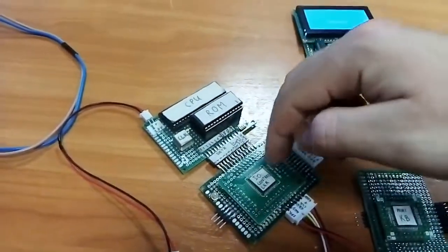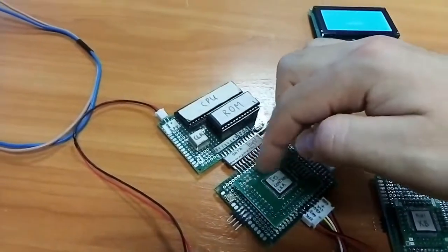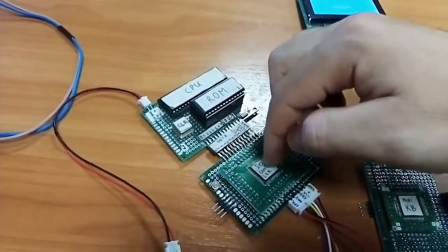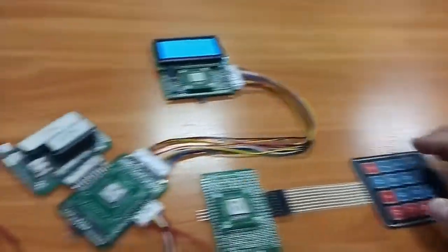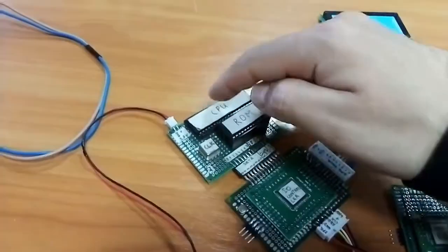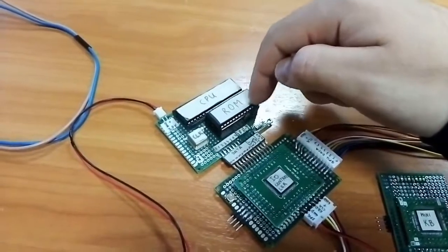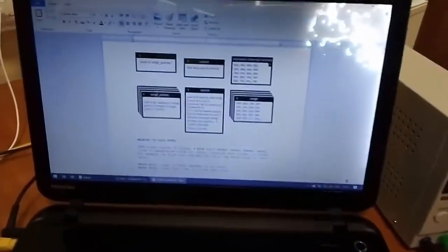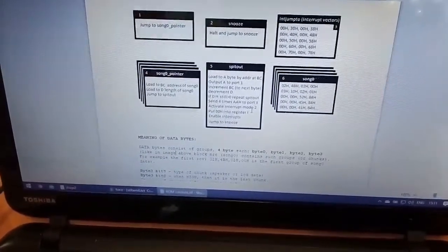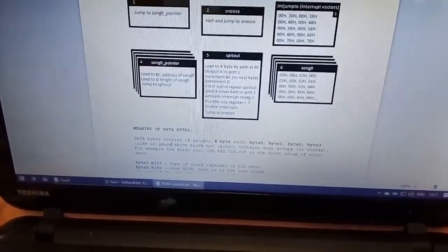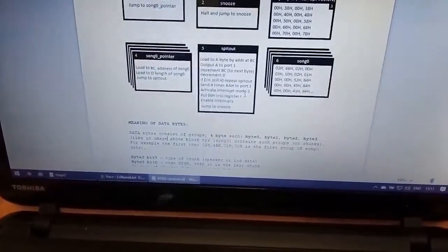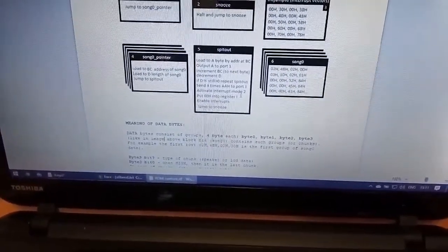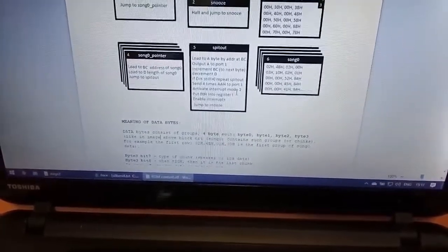The CPU was sleeping, now it's woken up by the interrupt from him, and the CPU straight away looks here at the data bus, and it finds here the byte depending on the key pressed, and with this byte the CPU is sent to a specific place in read-only memory depending on the song or the key pressed. That's interrupt mode 2. You can read about it in Google. You can find it if you put in the search Z80 IM2. That's interrupt mode 2.